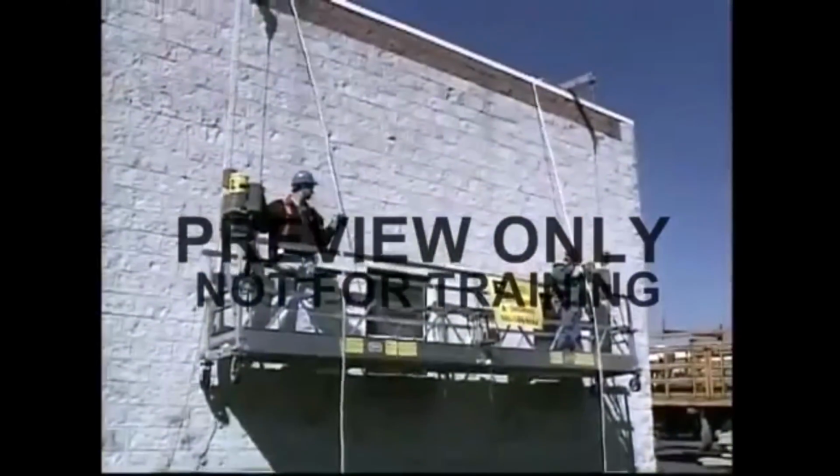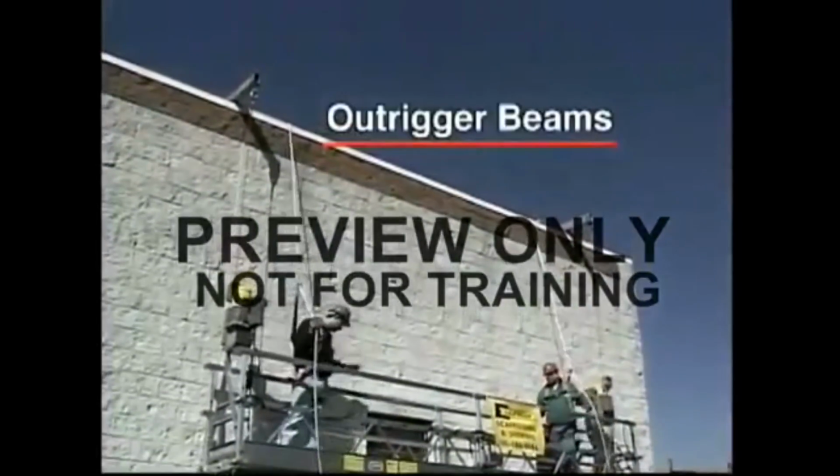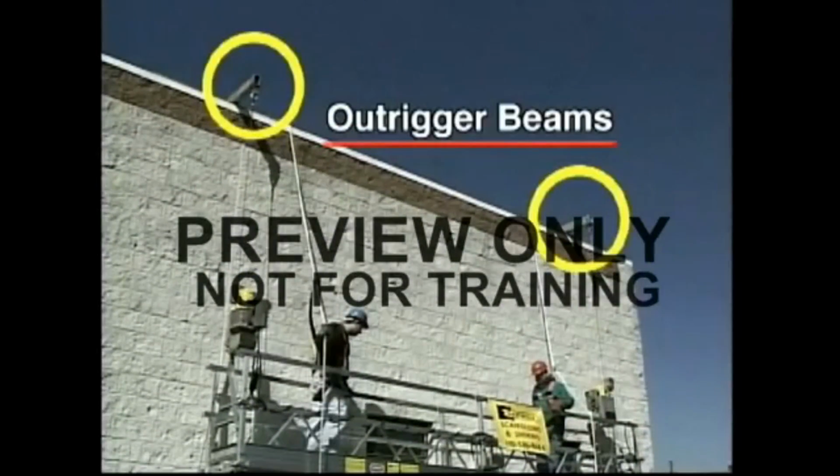When there are no points on the structure that can support a suspended scaffold, outrigger beams are used. These beams are anchored to bearing supports within the structure and extend the scaffold out and away from it.